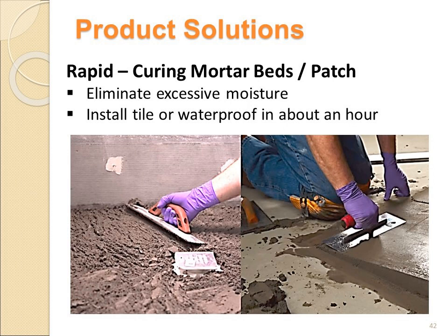As you can see here, on the left-hand side, there are mortars that dry within an hour, and it's not just drying, they're curing. If you put a moisture meter on them after an hour and a half, they meet less than 5% moisture as measured by the meter. So it's a very safe process to do your mortar bed, not have to wait for 4 days to let it cure out, and install your tile directly over it.